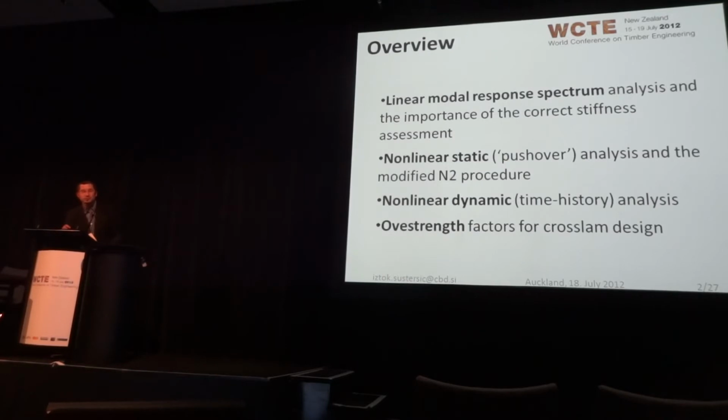Then we should move to the nonlinear static, or so-called pushover analysis, with the modified N2 procedure. N2 is the displacement-based design method incorporated into Eurocode for the last 8 years. Then we should move to the nonlinear dynamic time history analysis, and in the end I should try to tell you something about the overstrength factors, which should be used when dealing with cross-lam.